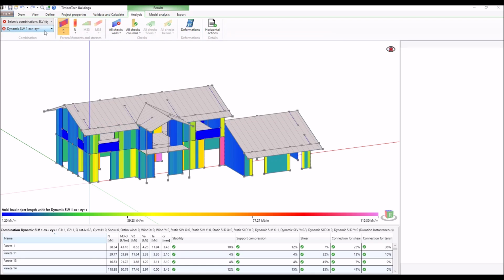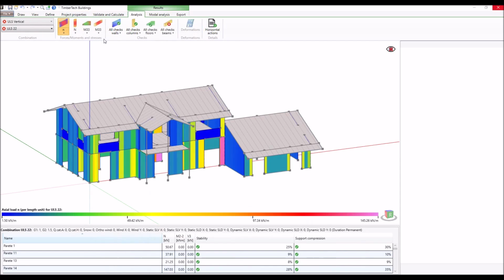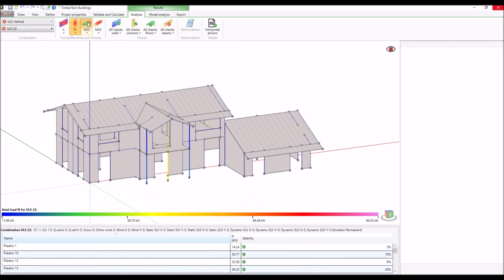The stresses present inside the structural elements can be recalled and represented on the screen by means of the buttons that are located at the top in the central part of the menu. There is a button for each type of element: wall, column, floor, and beam. Below each button there is a drop-down menu that allows you to choose what to display: the stresses, bending moment and shear force, or the displacements. These quantities are displayed by means of contour plots in the 3D model.